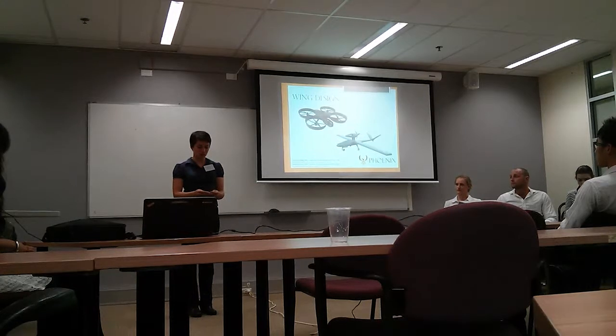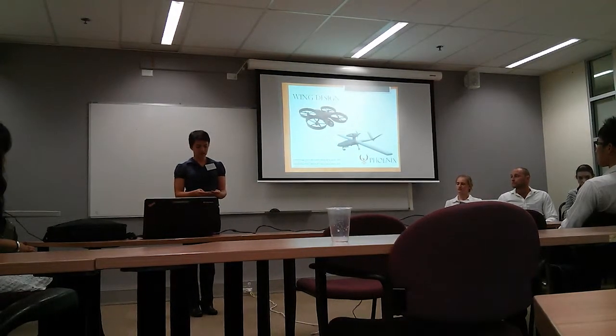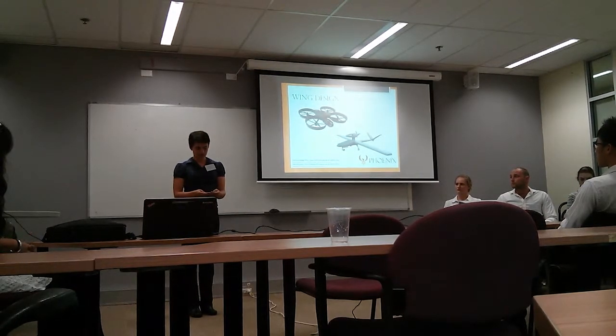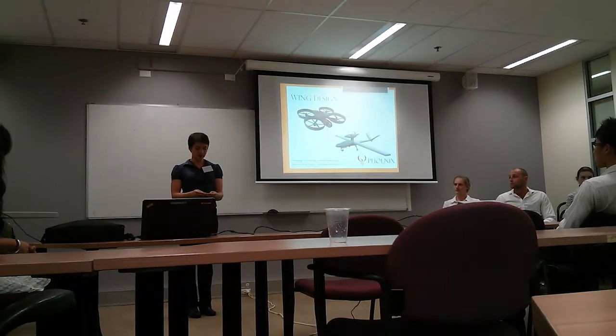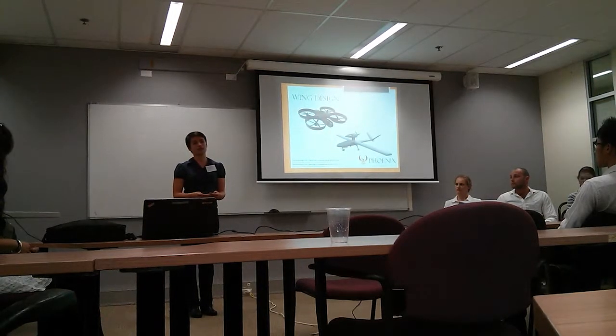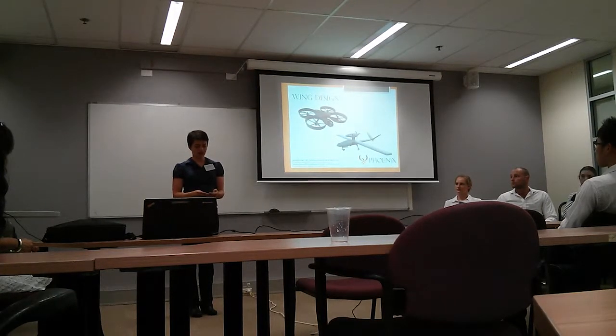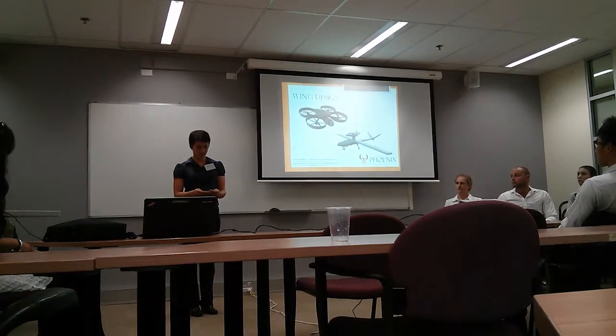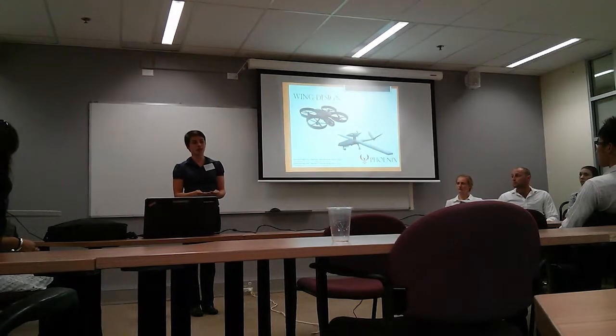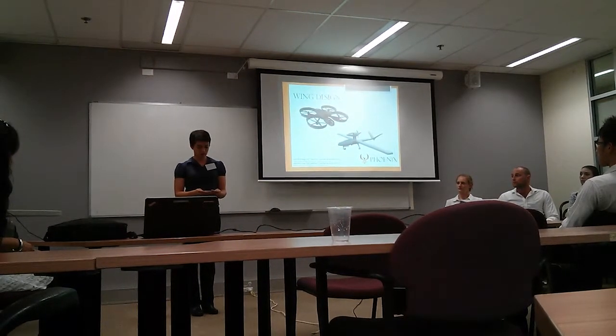Takeoff and landing is more complex in fixed wing UAVs since they need quite a bit of space. There are different methods of takeoff and landing, such as hand and catapult launch and parachute landing. Rotary UAVs are more versatile in that they can take off and land on any level surface without a lot of space. Fixed wing UAVs can carry a greater payload, are faster, and can fly for longer than rotary wing with the same power consumption. However, rotary wing UAVs have the unique capability to hover and fly close to targets.